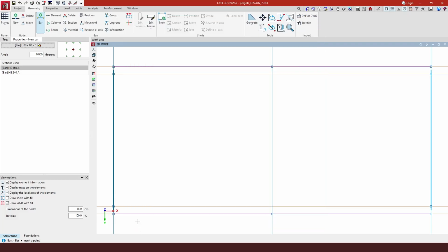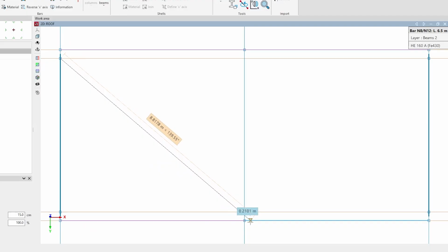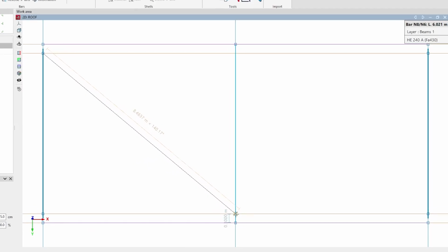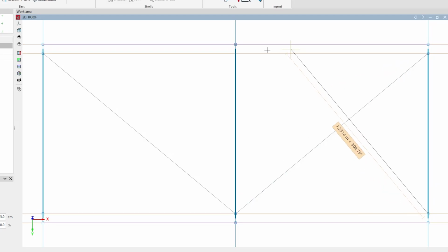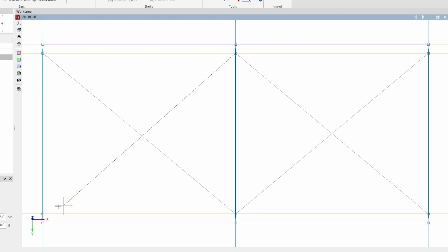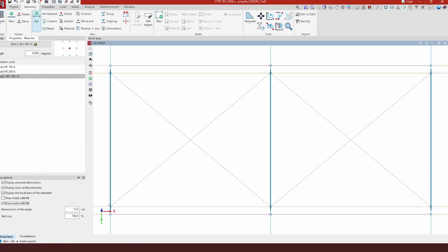When we click accept, we just want to snap this node and make the crosses. So here, since there's a reference line, it's very easy to insert. Now it continues with the insertion. So if I want to move to another node, I just have to do a right click and start over in this other node to insert the braces.